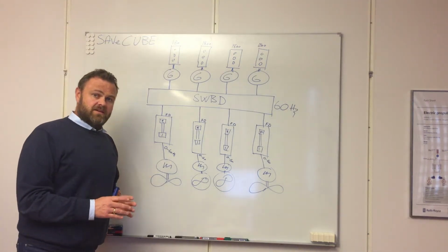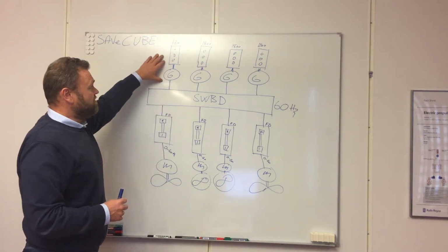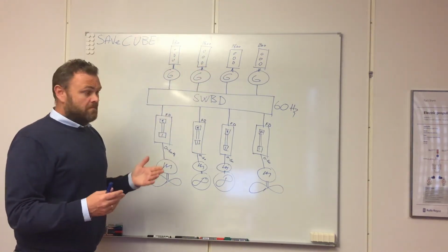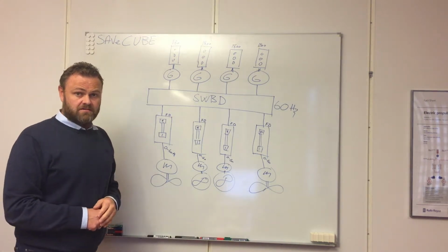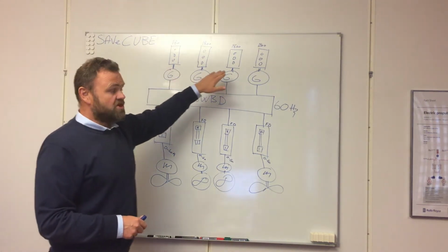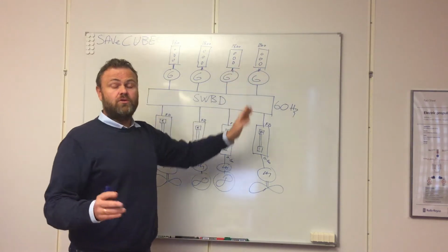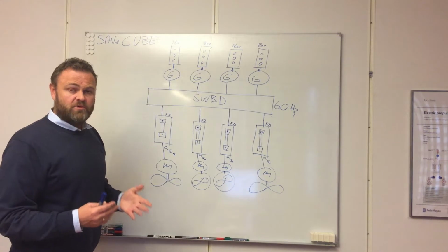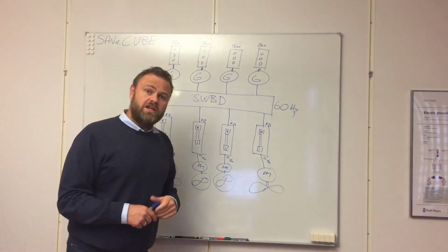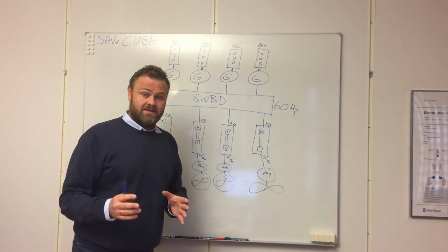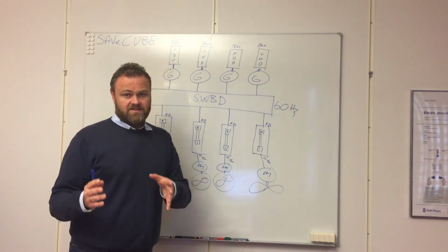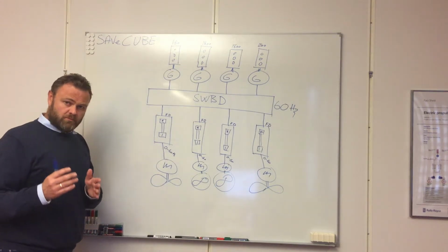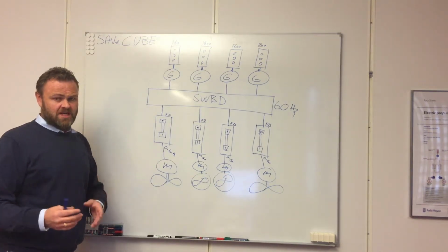In cases like that, you will have engines maybe running at a very low load, maybe as low as 20% load on each engine, because they have to run due to regulations or safety reasons. If it is a DP operation or a redundant propulsion class, you need to look into the class rules and have a look at the redundant propulsion requirements and the DP requirements.